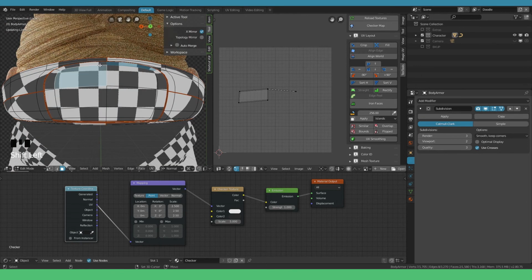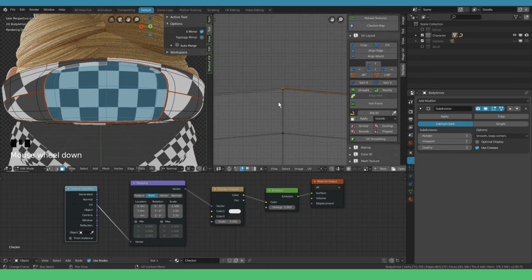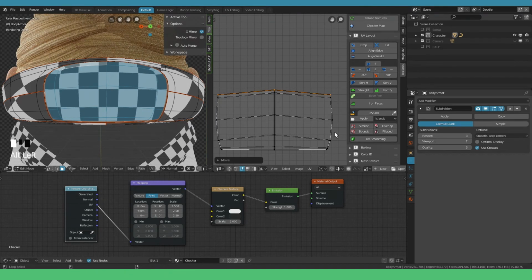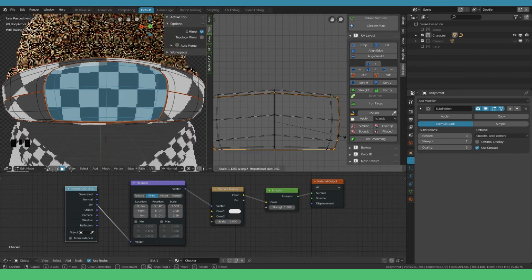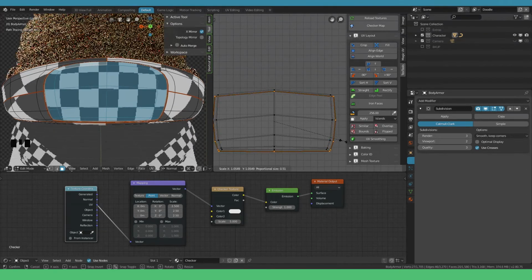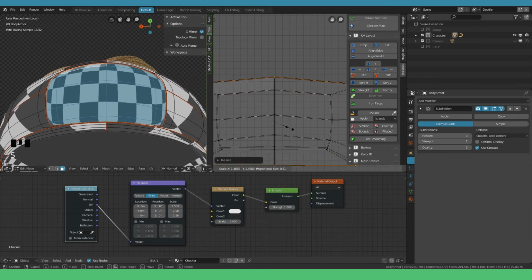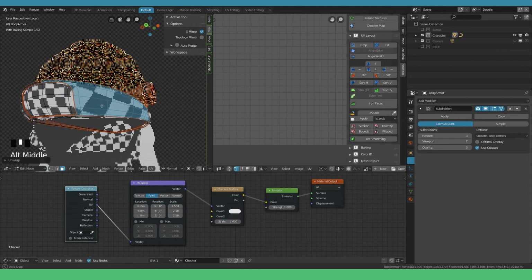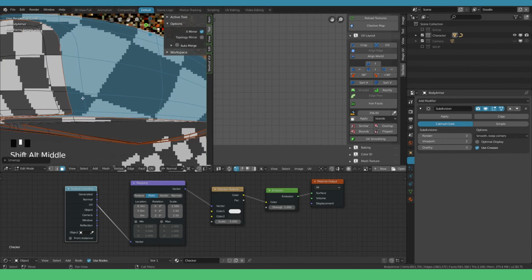Yes, this worked like a charm. The projection from view was good, but we need to tweak the surrounding edge loop. What I'm gonna do now, in the UV editor, I'm gonna move some vertices around. We can use the same controls as in edit mode: G for moving, R for rotate and S for scale. Let me skip forward in this edit, so I can show you how I manipulated the UVs for this piece.